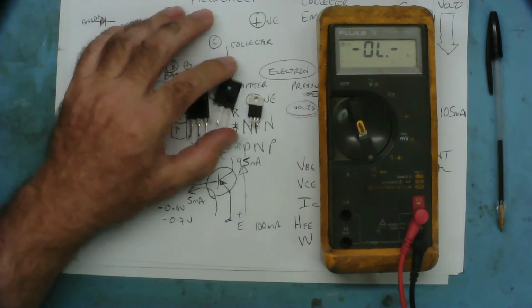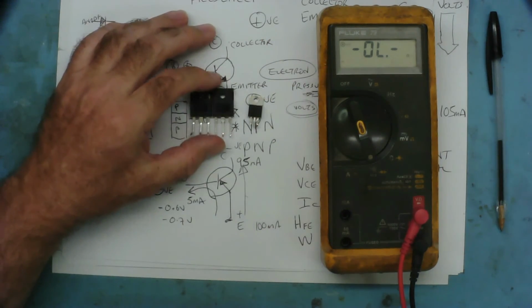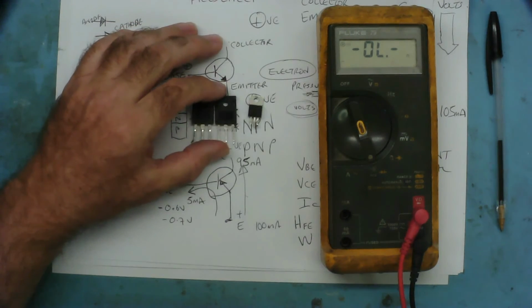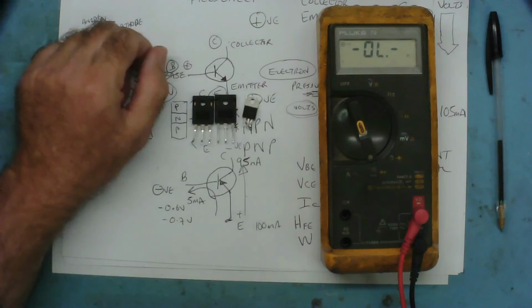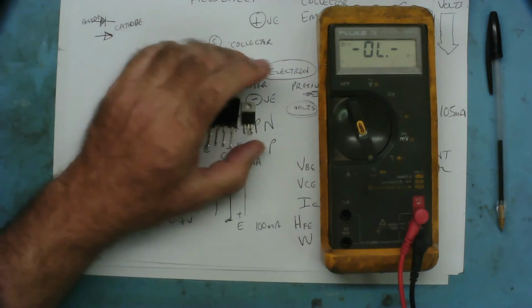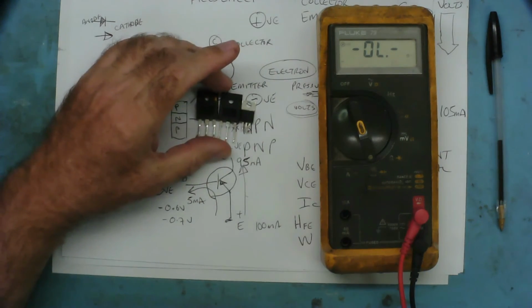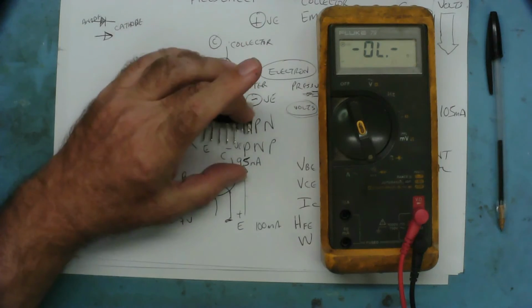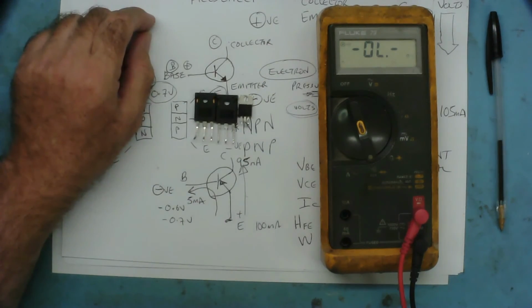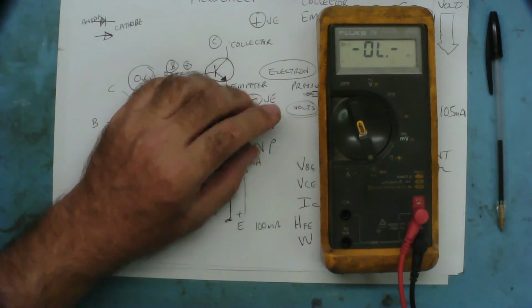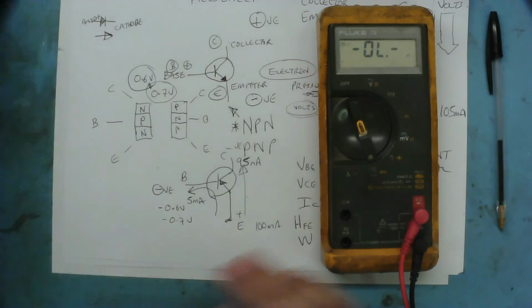So when you're changing these transistors, a couple of things. If there's a little rubbery or plastic washer on there, or a little plastic insert where the bolt goes through, make sure you put them back when you replace them. Change the heatsink compound obviously as well, but make sure you put the insulators back in, because if you don't do that, you're going to regret it. Okay, so that's a little bit about wattage.